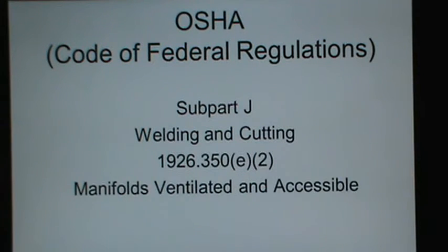Let's drop down to 350E2, manifolds ventilated and accessible. 350E2, fuel gas and oxygen manifolds shall be placed in safe, well ventilated, and accessible locations. They shall not be located within an enclosed space.